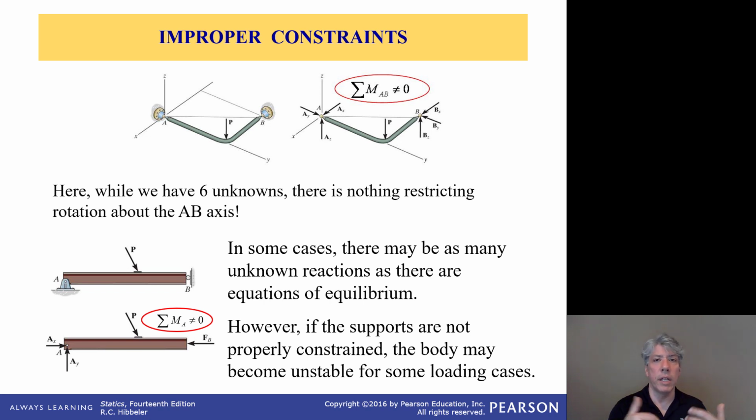It was interesting, though, because there was still a problem. Because of the relatively low stiffness of the supports, when you get up in the treehouse, the whole treehouse would rotate around. You could run and stop all of a sudden. It would very uncomfortably just sort of rotate about the tree for what felt like an excessive amount of deflection. My solution to that was to add another bracket on the other side of the tree, and that took care of it.